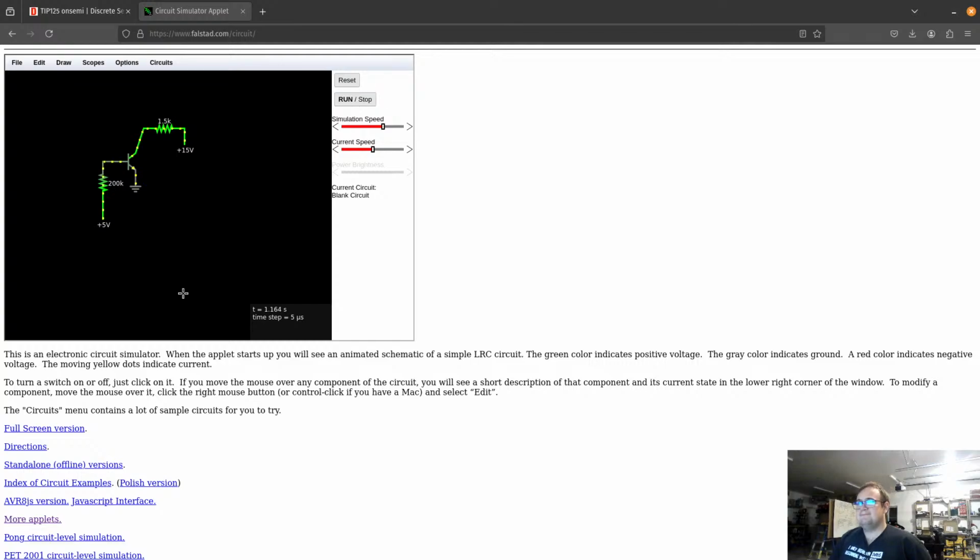Let's see. So 3.2 volts is being sort of burnt across this 1.5K. And then at VC, we see 11.7 volts. Then VE, obviously 0 volts. So I was pretty close to right, 12 volts there. That's interesting. I don't know. That's a bit of an odd circuit.